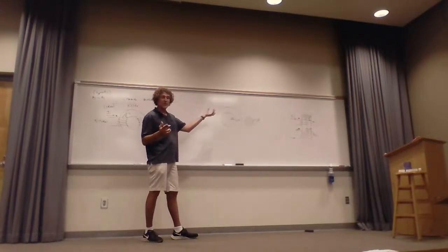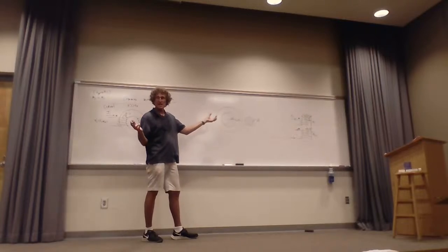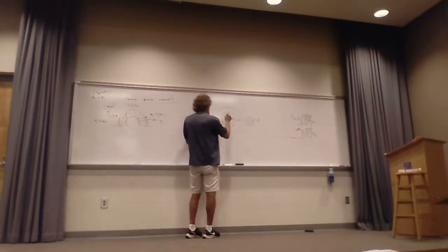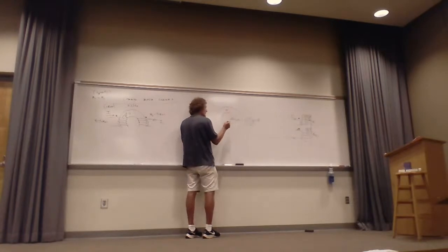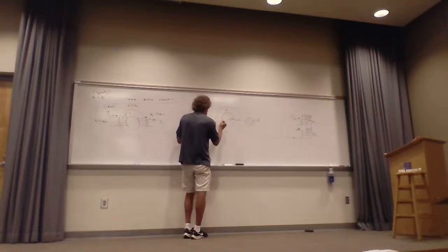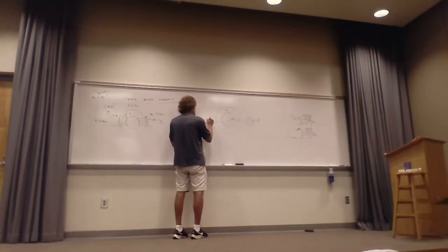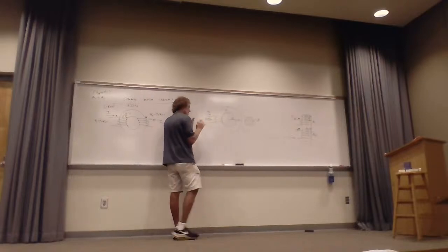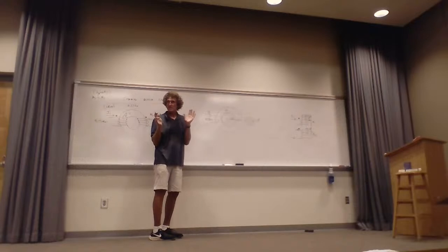I could give you a radius for that core, and you could figure it's pi r squared. But you all follow me on this, class? Doesn't matter. And it has some value of mu. Then I wrap it with turns. I'm going to say I have N turns here, and I'm going to put a current I here. I only did one set of coils because I'm going to get the self-inductance.